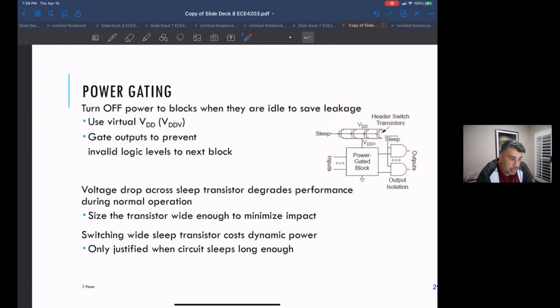So I think the note to self is, the effective power consumption reduction techniques are also pretty dangerous. And those are clock gating and adjusting the supply or turning off the supply voltages. And you have to be really, really careful with those, because it's really easy to mess up your circuit when you go into these modes.